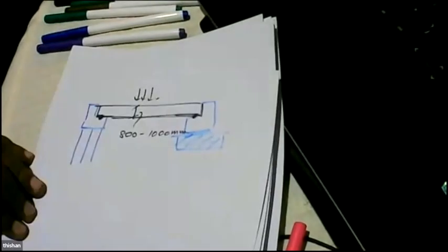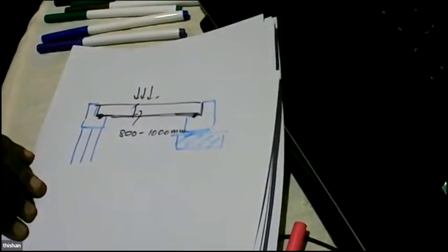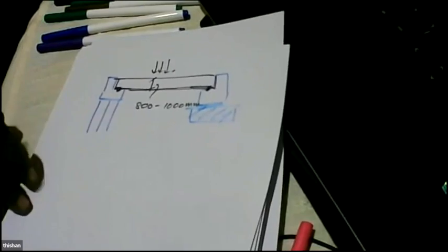But whatever happens, again you have to look at some other advantage, because we are going to simply support the bridge. We know, the moment you simply support a bridge, the variations that occur in the support have no effect on the bending moment that occurs in the bridge or the slabs. So when you look at it that way, again you can see there are particular advantages.